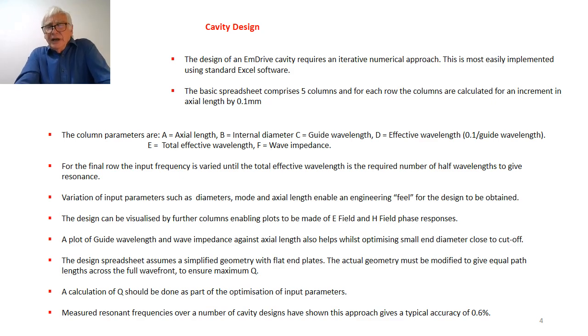Now, we've already said that you don't actually get a successful cavity with flat end plates, so you actually have to modify the geometry of the design to incorporate these curved end plates to ensure that you get minimum phase shift across the full wavefront, and this will ensure that you get maximum Q value.